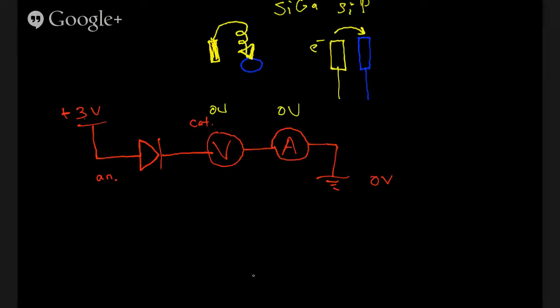and have a positive potential, we'd end up with not quite 3 volts. There would be a drop depending on the type of diode. This is not a perfect conductor. It would have some sort of voltage drop in it, and we wouldn't get quite the same current capacity as well.